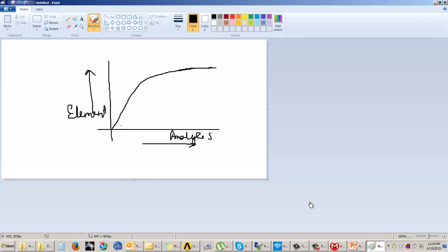So as the number of elements are increasing, you will see that your answer is also becoming much more accurate. We can understand over here that as the number of elements increase, the accuracy of the analysis also increases, but after a certain point it becomes almost constant. So from this graph, you can decide what should be the optimum mesh size.